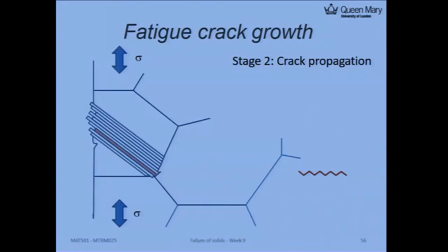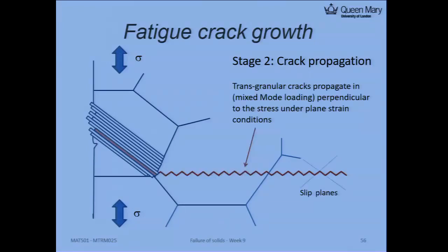And what happens after the initiation? For example, here the slip band is initiated. There is a small micro crack initiated here, and it will grow into the adjacent crystal. For example, here. Like we said with the maximum hoop stress, eventually your crack will be in a direction normal to your loading stress. That's why it's a horizontal line here. So it will grow perpendicular to your loading axis, in this direction and in a kind of zigzag manner. So eventually this crystal here will be fractured.